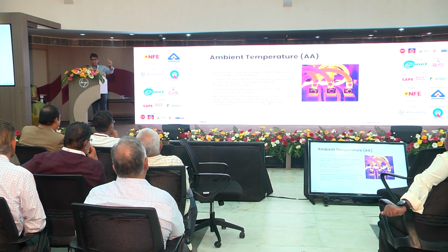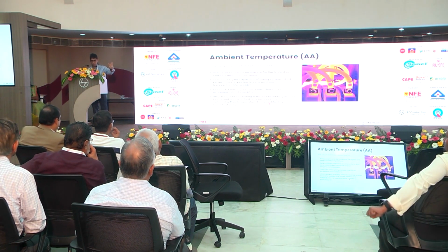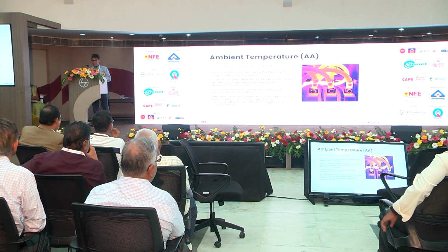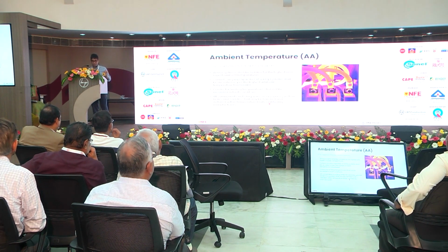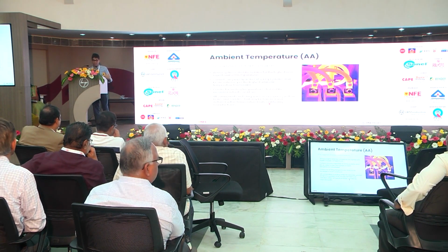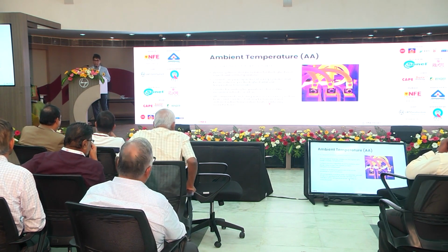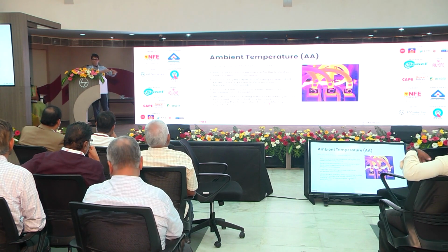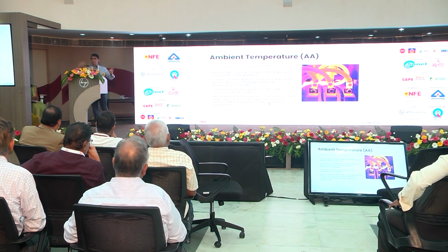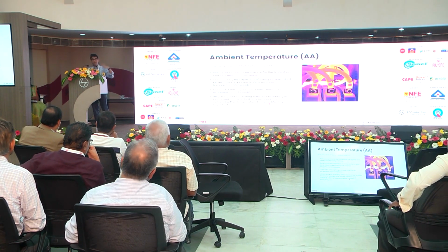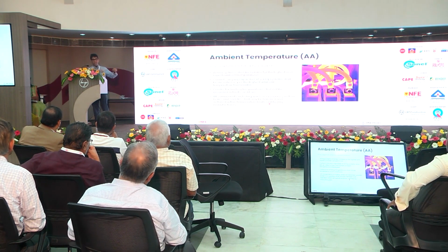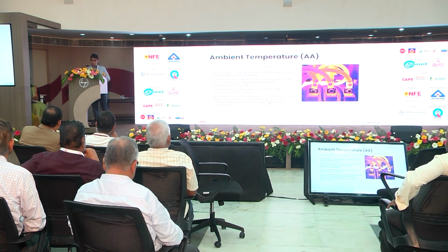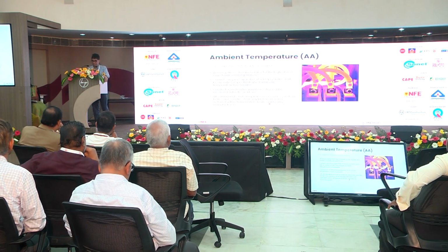Additionally, all the wires, accessories, junction boxes, and saddles should only be installed in temperatures limited by the manufacturer. There is some understanding in the market. But even handling and storage, you cannot leave your cables and cable cleats out in the sun. Many times the electrician will come on site, someone calls them inside, they leave it there. Then immediately it has exceeded the limiting temperature and can no longer perform to the relevant manufacturing standard.